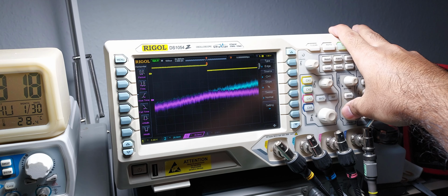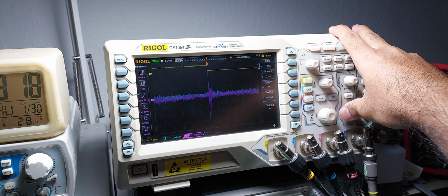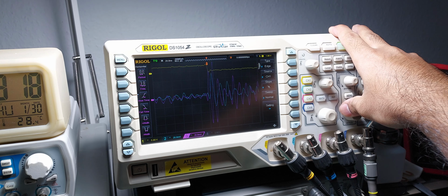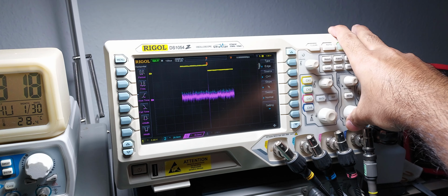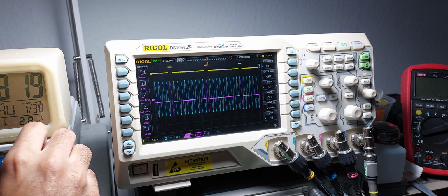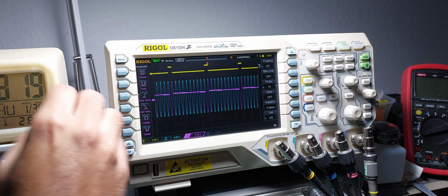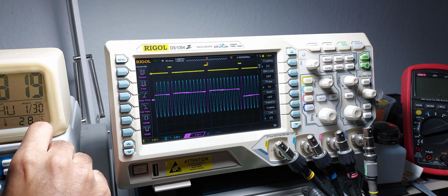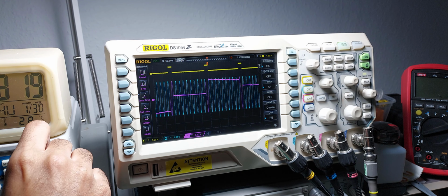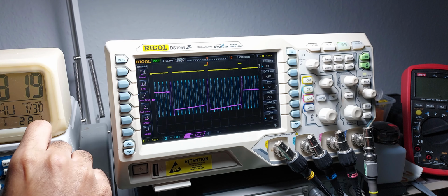Using a smaller input signal demonstrates that there are no artifacts when the circuit switches from sample mode to hold mode. And as far as I can see, there is no droop over the 175 millisecond hold period, unless I artificially induce some by changing the probe to 1x mode with a 1 megaohm input impedance.